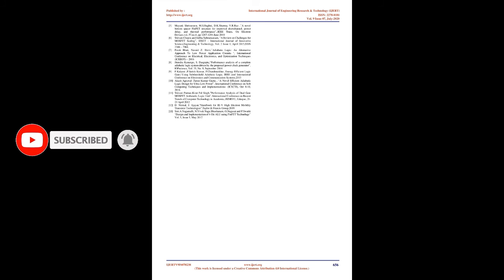A pair of pull-down MOS network and pull-up MOS network forms the logic in ECRL. Both pre-charge and evaluation are conducted concurrently in this technique. It removes diode use and thus has less energy dissipation. It has weak zero logic due to the threshold voltage of the MOS. Therefore, the ECRL circuit has less noise margin. Figure shows the ECRL adiabatic logic overall block diagram. A simple inverter circuit implementation using the ECRL adiabatic logic is shown in Figure 4.3.